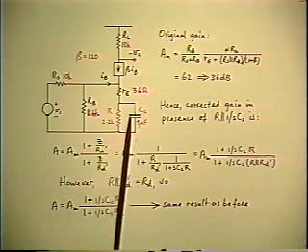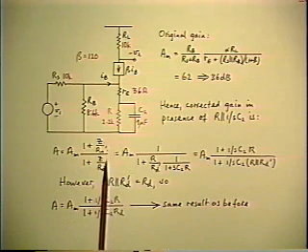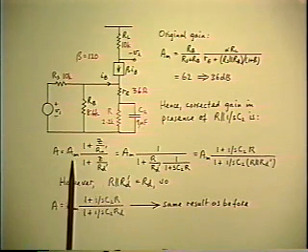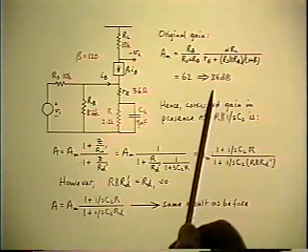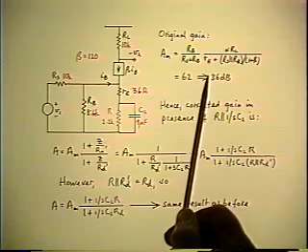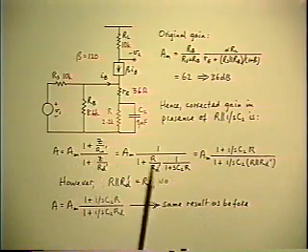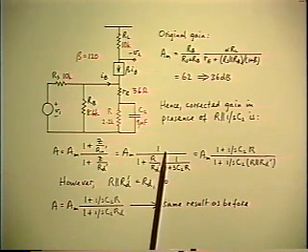But you don't have to know that until the last step, because you've already calculated the RD prime and the RN prime. So now the reference gain using the series form of the theorem is AM this time, corresponding to infinite frequency, and the correction factor reduces to the denominator part only because the RN prime is infinite.